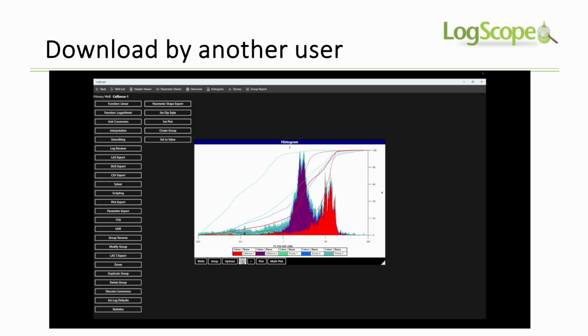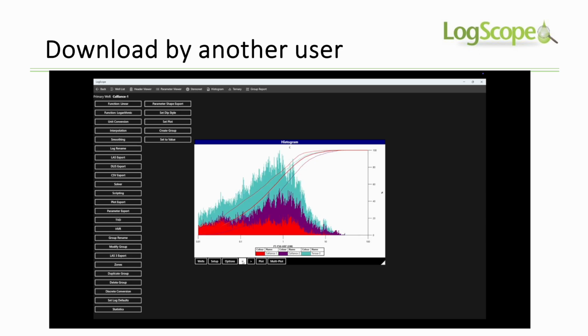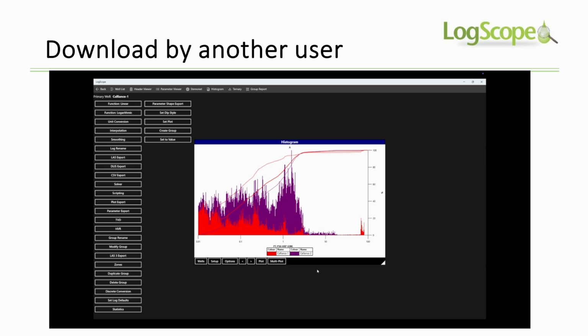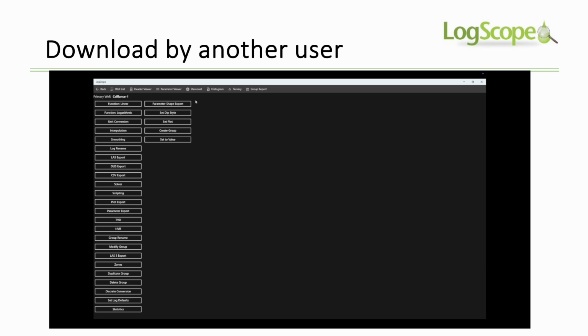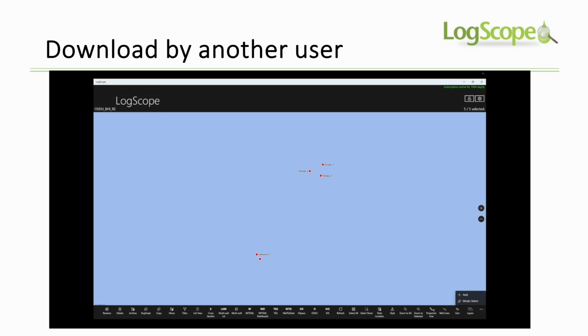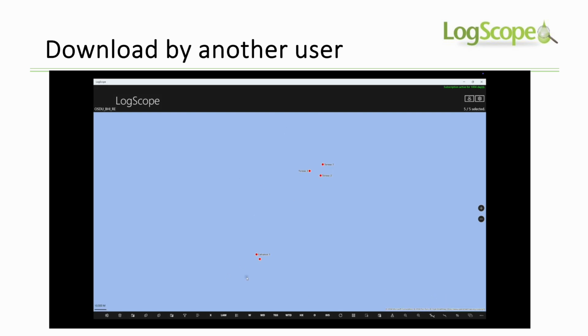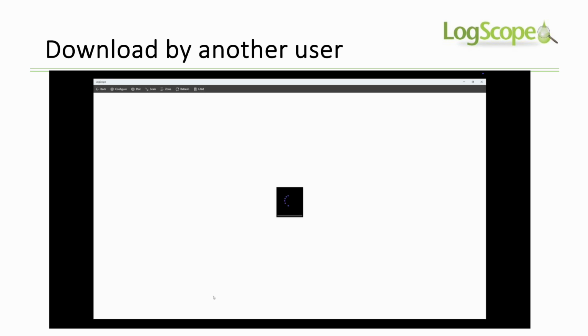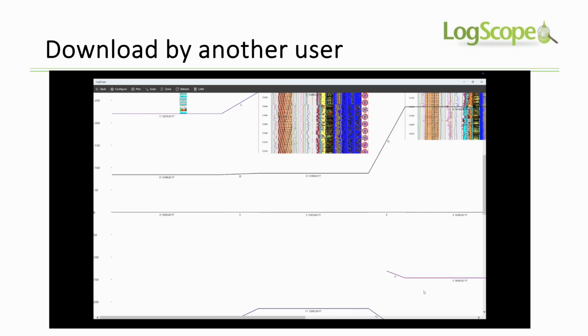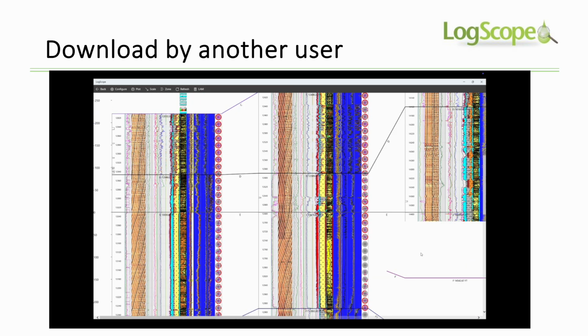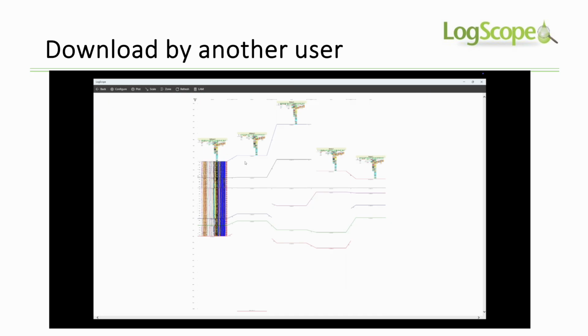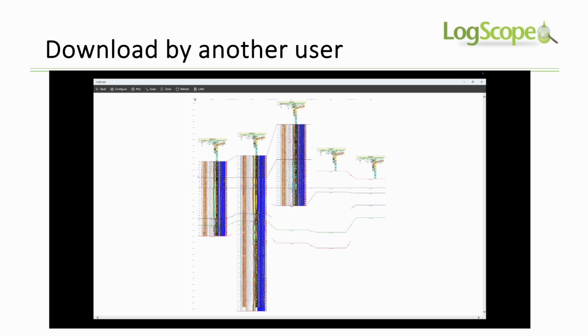Once we've done that, we can then go and look at the wells in cross-section so that we can actually see what's going on. So basically we go here and we set up a cross-section from southwest to northeast, and we plot the data and we look at the cross-section which I've got here, and if I expand it, it's there. And that's one way to see the data in one go.